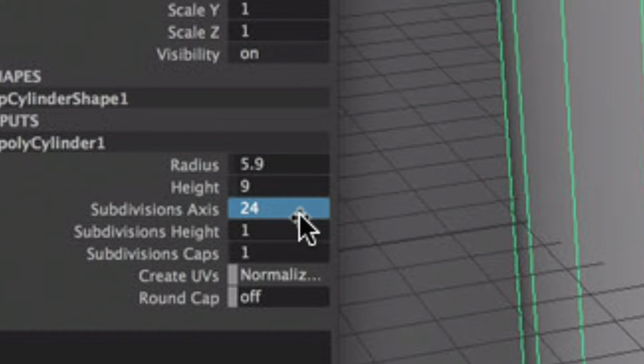Would you happen to know if this is pretty much the same concept on Windows? Identical, yeah. The only key binding that's different on the Mac and the PC is the Option key and Control. I apologize. On the Mac, we're Command button centric. The Command key is equal to the Control key on the PC, and the Option key is the Alt key on the PC. So those are really the only two differences. Everything else is the same. That's going to help you out, save some frustration, because you enter in a value, hit return if you want to confirm it, and go on.